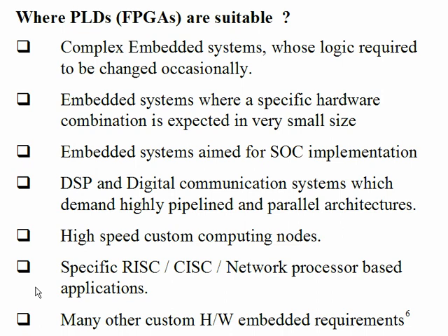Do you have pipelining in the 8085 microprocessor? That's my question. There is some level of pipelining in the 8085 microprocessor, but that is not pipelining at the ALU level. It is only in terms of the read and execute cycles. It is not visible to the programmer because that is purely at the hardware level. When you are fetching one instruction from the external RAM, some portion of the execution of the previous instruction also will be done in that time.